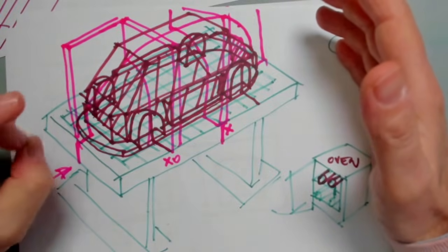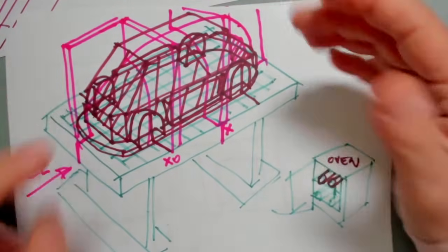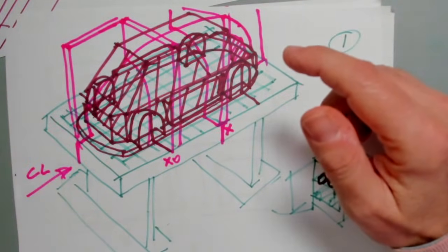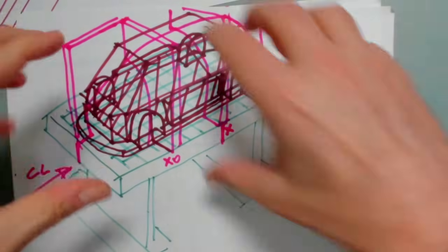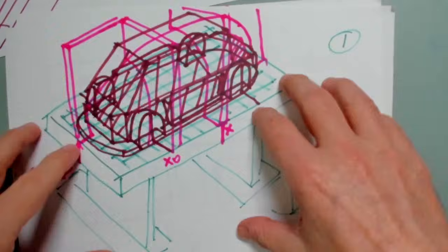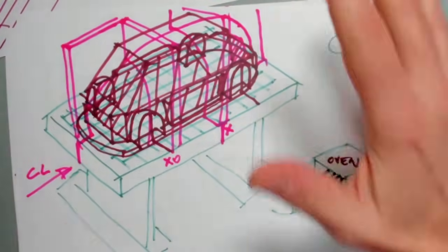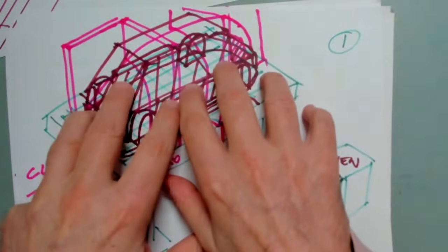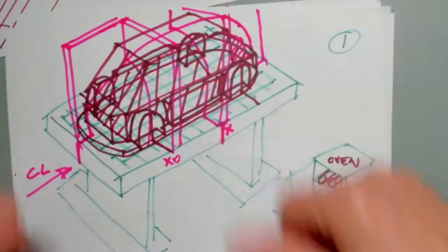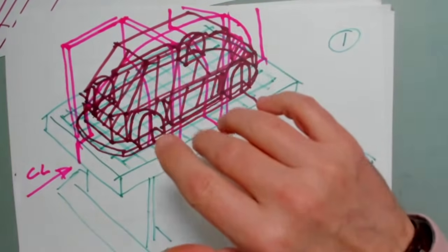Yes, interiors are made of clay modeling too, of course, especially at the beginning of a project, in full scale. There is also a back structure made of wood, full scale, with a seat and so on. Everything is made of wood, and then in some areas you put soft foam, and then you apply clay. But we do milling at work.